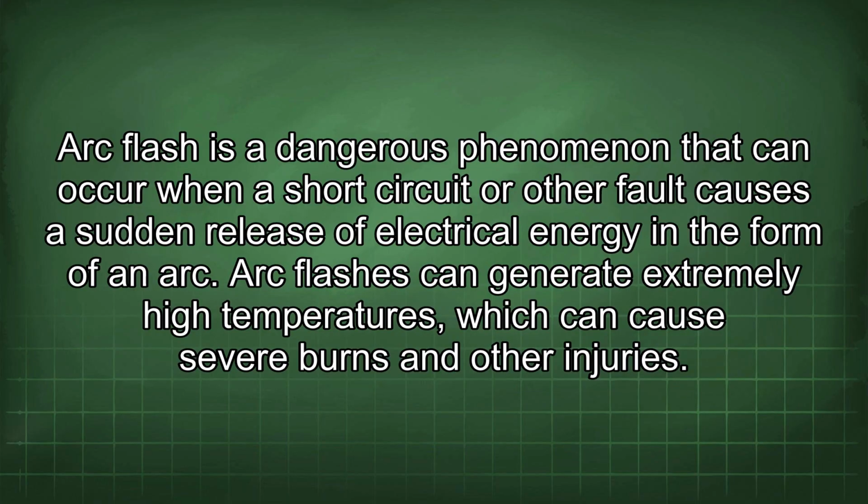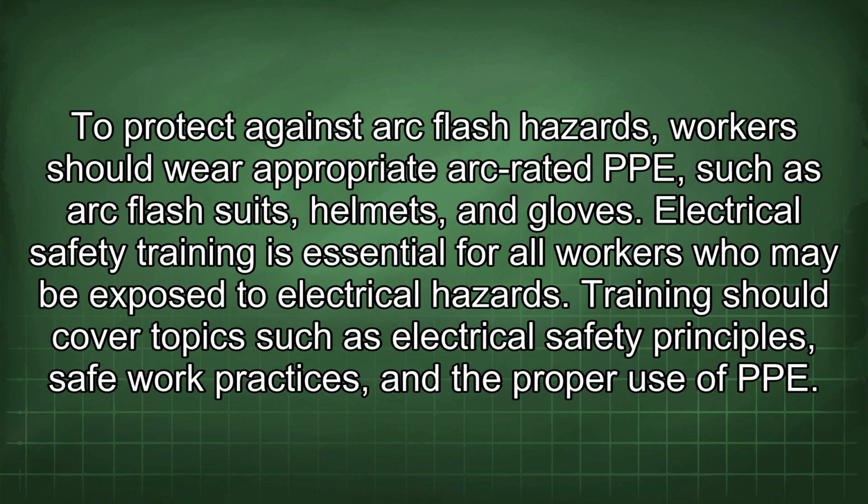Arc flash is a dangerous phenomenon that can occur when a short circuit or other fault causes a sudden release of electrical energy in the form of an arc. Arc flashes can generate extremely high temperatures, which can cause severe burns and other injuries. To protect against arc flash hazards, workers should wear appropriate arc-rated PPE, such as arc flash suits, helmets, and gloves.